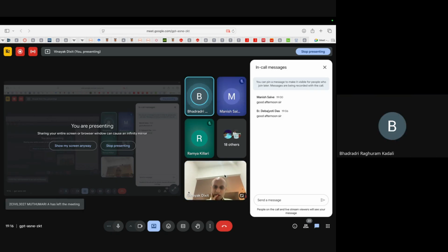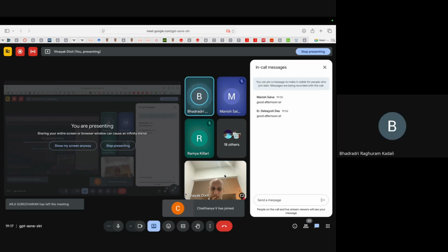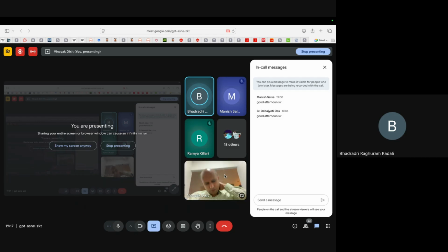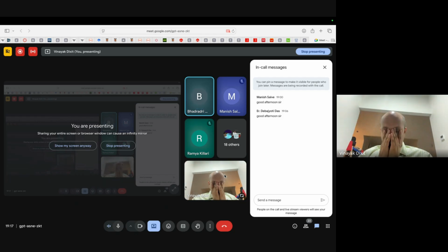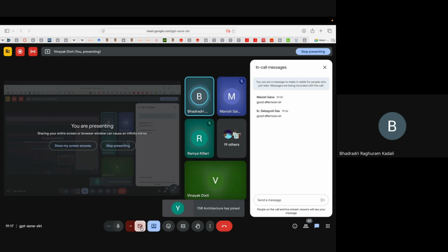When you're looking for the value of time or even the vehicle operation cost, generally it is expected that it may change with the region, like city to city, specifically the value of time. Yes, correct. But the codal provisions, like IRC SP30, even the 2019 version, have given standardized values for the value of time. The vehicle operating cost also, they have taken different examples and given different standards.